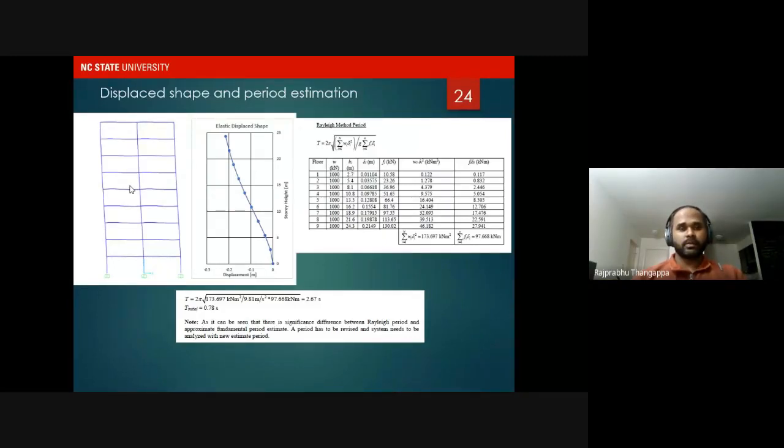Think of replicating this procedure for a complicated structure, and mostly in reality we might not have symmetrical frames, and there would be additional complications in the way forces are transferred, and we would have to apply this procedure in different directions of the building and consider the critical forces to decide on the respective design cross sections.